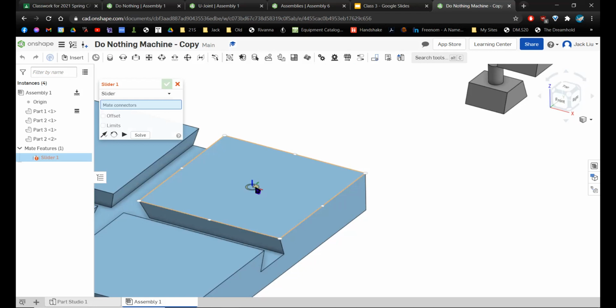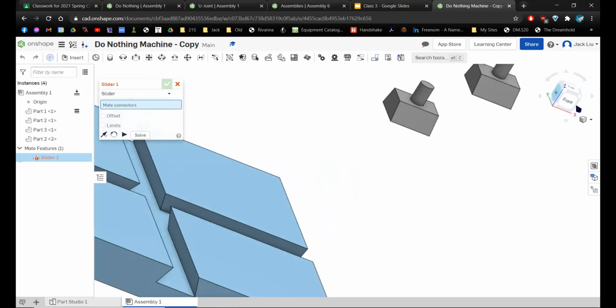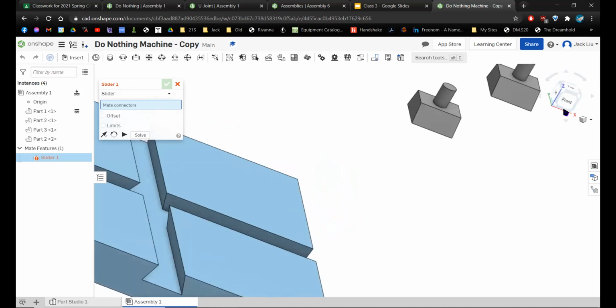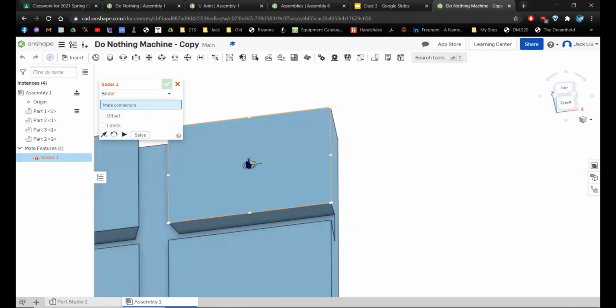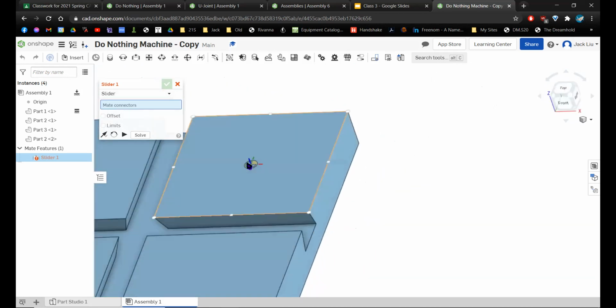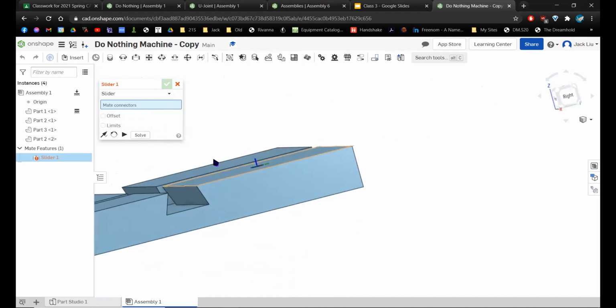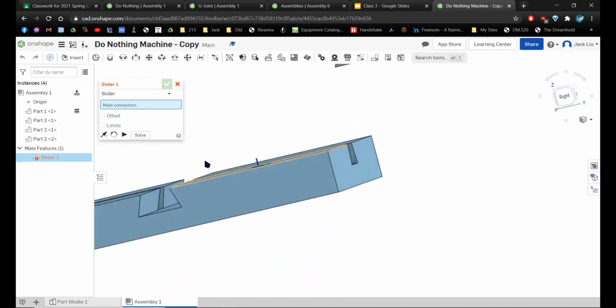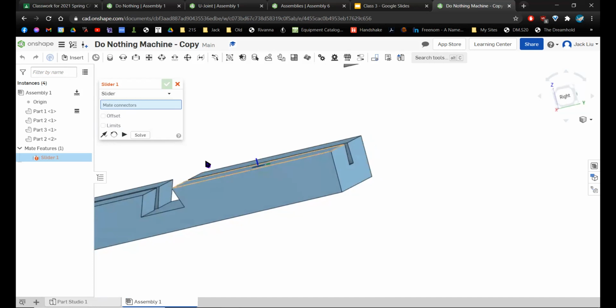These represent axes, like X, Y, Z axes. So you can also see these colors, the red, green, blue, on your navigation cube right here. Notice it says X right here, Z there, and then Y there. So red is X, green is Y, blue is Z, right? That's exactly what these lines are telling us. So if I look, the Z axis, the blue line, is sticking straight up, right? Because the Z axis is going up.